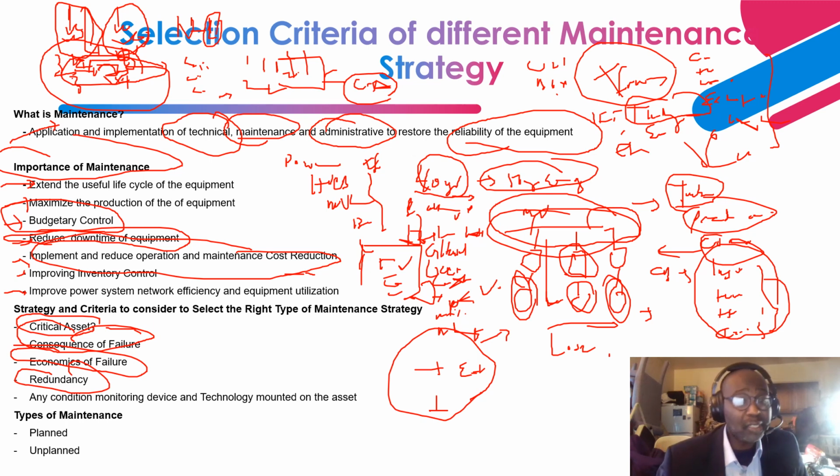So, for instance, if this transformer's condition is very good, based on DGA, electrical testing, inspection, infrared thermography testing, and predictive maintenance survey, then I can say, okay, I can take this transformer out of service. I can give it time-based maintenance or condition-based maintenance, and when I put it down for time-based maintenance at a 6-year interval, it means I can confidently take this transformer out of service and transfer all its load, right?